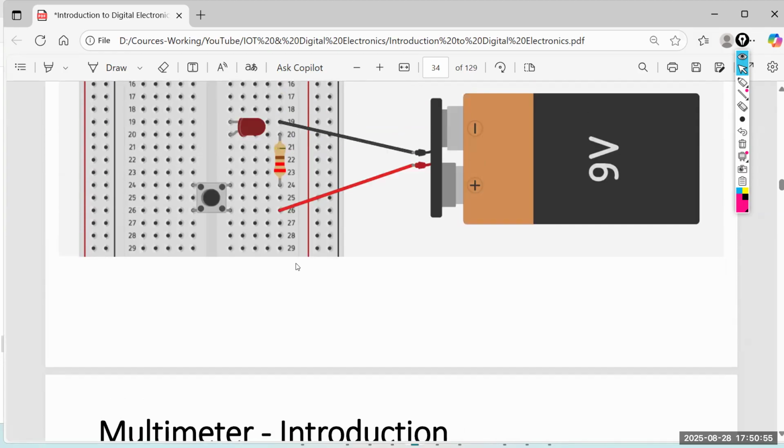Okay, right. So we are working with a virtual environment, but when you work with real physical electronic components, with your breadboards and real resistors and so on, sometimes it may not work, right? Maybe you have not fixed it properly, because there can be loose connections. Virtual world is easy; reality has practical problems, right? Maybe your battery is drained out and it's not giving 9 volts. Maybe your wire is broken somewhere. Who knows? Maybe your LED is not working.